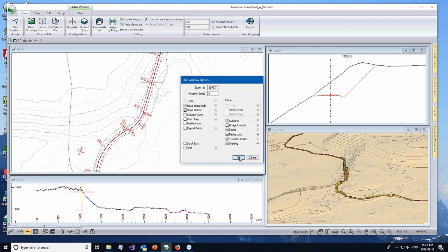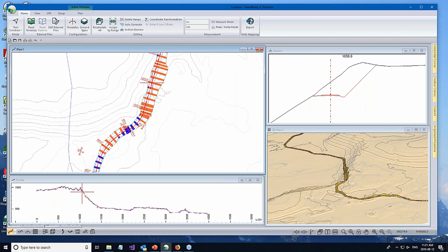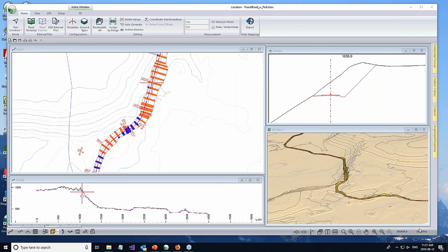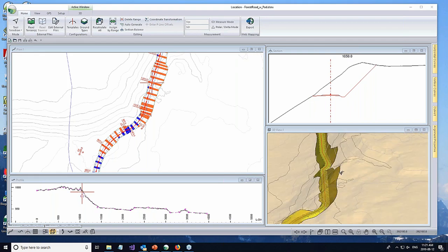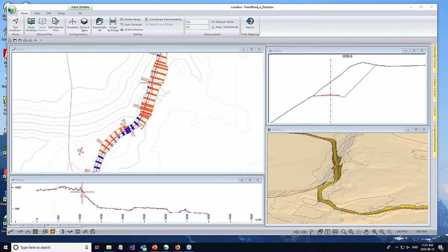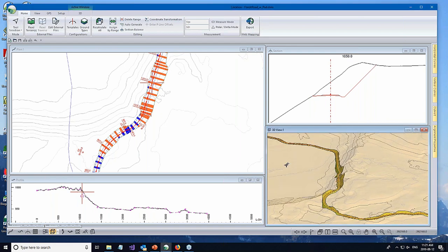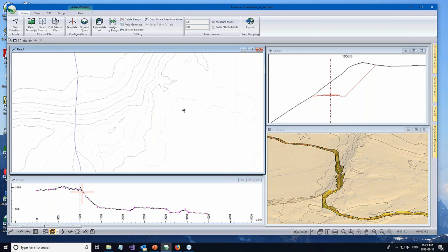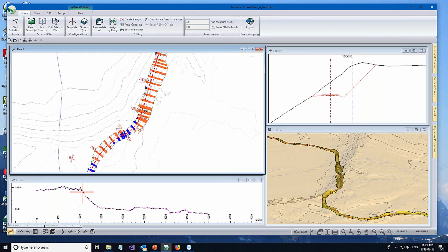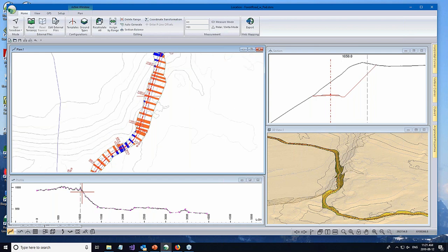We'll have a look. This road, by the way, has got some steepish sections. It's going through a bluffy area, and it's dropping down off a plane. So one of the useful things about showing cut and fill is you can quickly see when a road is in full bench cut, and you can move the road with that visualization.